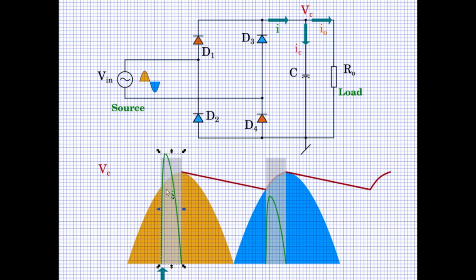Of course, I will discuss the protection circuits and see how we limit the turn on current surges. But keep this in mind that all is not rosy and all is not well and good with the circuit that we have just discussed. The turn on current surges can be pretty high, and it could be a big drain even on the wall socket outlet. They have to be rated for such high currents. Therefore, we would like to put a series impedance somewhere here and limit the current surge.